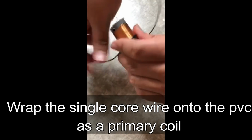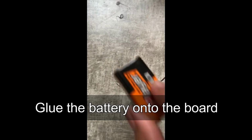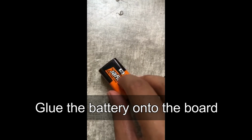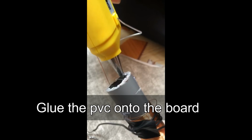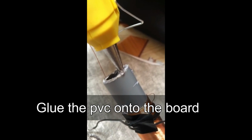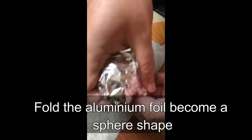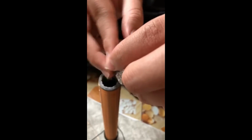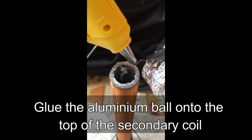Wrap the single core wire onto the PVC as a primary coil. Solder the battery wire with the emitter of the transistor. Next, connect the 9-volt battery and glue it onto the board. Take the bottom end of the PVC and glue it onto the board. Take and fold the aluminum foil into a sphere shape. Connect the upper primary coil with the aluminum ball and then glue the aluminum ball on the top of the PVC.